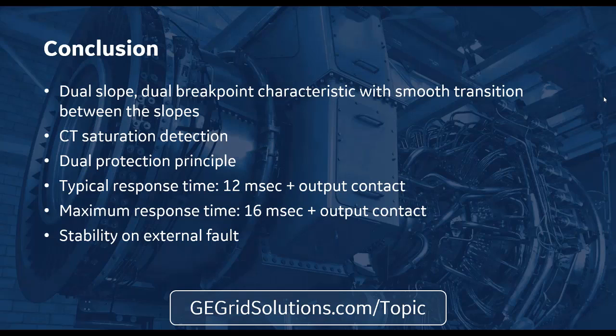So it all depends. There's no simple answer to say it shouldn't be applied at 480 volts, which typically it's not at 480 volts. There's economics too, right? It's an expensive scheme. So at 480 volt, there are more economical solutions, like using an arc flash relay with a light sensor, than applying a bus differential relay. So it depends.